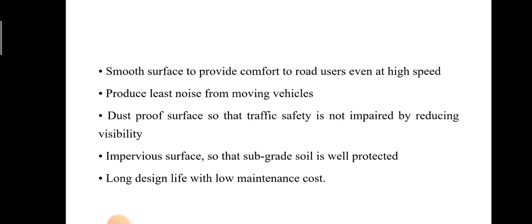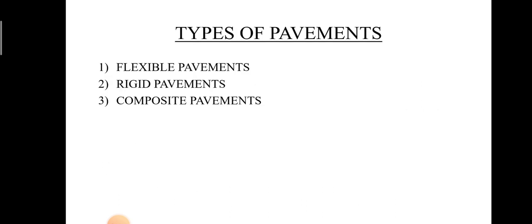Then it should have a smooth surface to provide comfort to road users even at high speed, and it produces the least noise from moving vehicles, and its surfaces must be dust proof so that traffic safety is not impaired by reducing visibility. Then the surfaces should be impervious so that the subgrade soil is well protected, and it should have a long design life with a low maintenance cost.